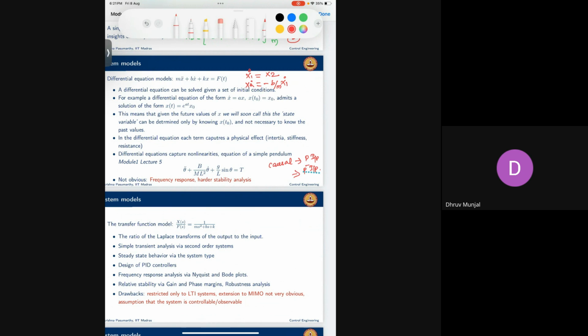You should know what all those previous inputs are. How will you know? In a practical case, you cannot keep a recorder or some other memory storing device to do this, right? So practically we can explain this previous set of inputs as a state trajectory. So even with only one state, x1 or some x state of the system, it knows how the system was previously.